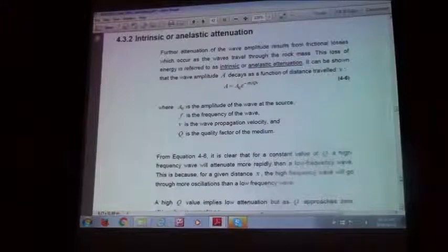Now that frequency is very important in telling you about the source. Its corner frequency tells you what the dimensions of the source are. And from that you can start working out other things when you use your energy and your moment, combining them to get an idea of what your stress drop is. What is the change in stress with that seismic event? And so we use these parameters later on to derive a whole lot of other parameters that we use to try to characterize our rock mass.